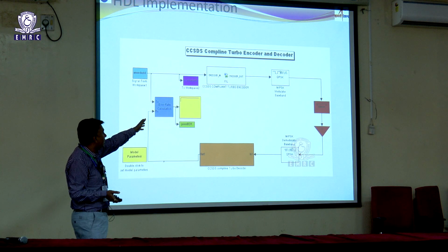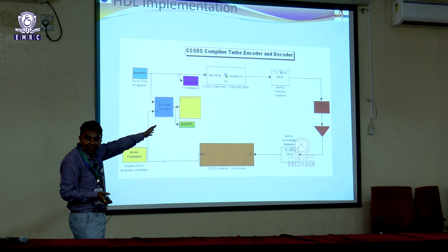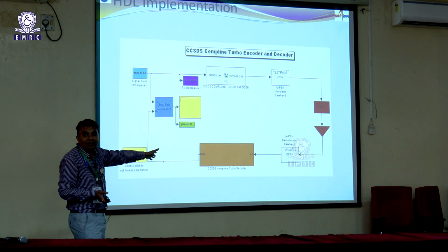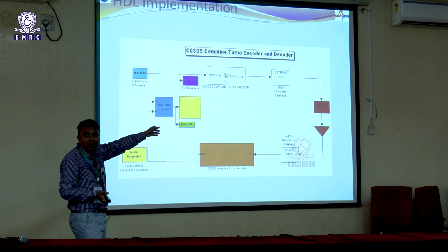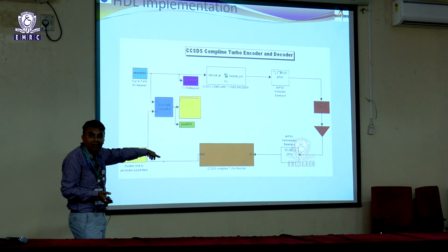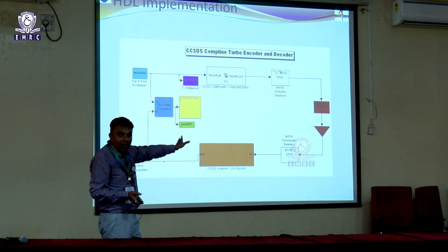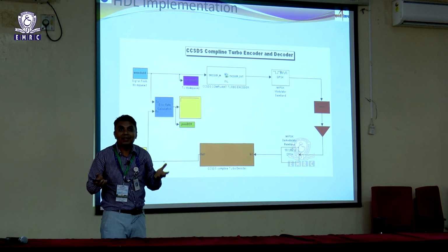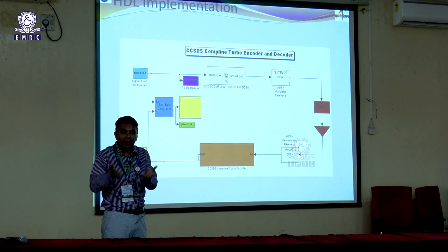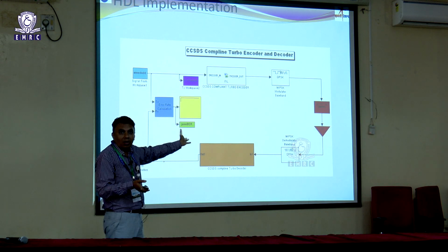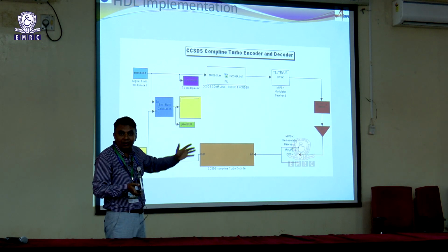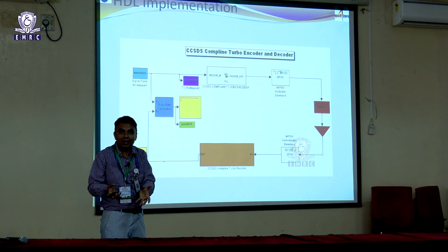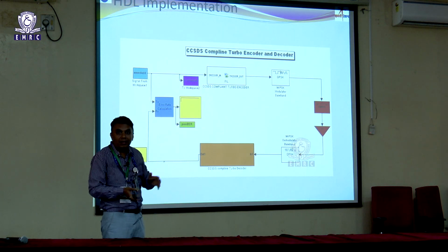So, the encoder is running inside the FPGA board itself, and the decoder is in the Simulink environment, but we are verifying the HDL encoder implementation in the Simulink environment itself. The advantage of this approach is that without having a physical source and sink, because MATLAB has n number of sources and sinks, channel models and noise sources, we don't have to buy the physical hardware for that. That validation you can do in the Simulink environment.